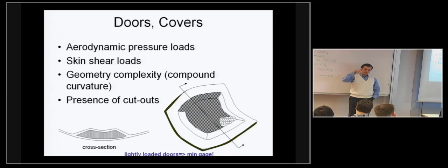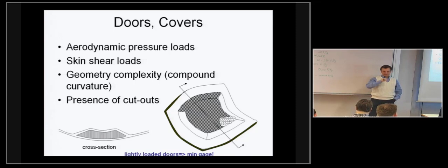This moisture goes through much more easily and can cause all kinds of problems, not only by reducing the local stiffness because the structure swells, but also because if you then freeze that moisture, it expands and can cause all kinds of additional problems.